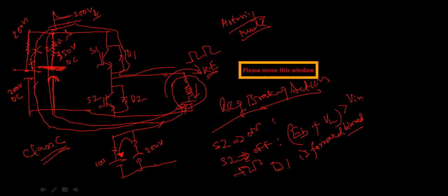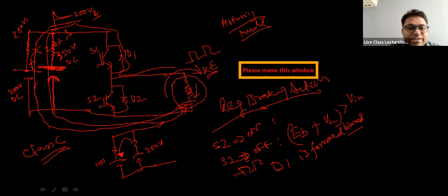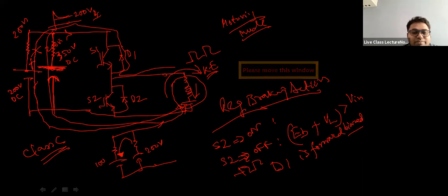The battery has a limited number of charging-discharging cycles. Only a very small quantity of power can be held by the capacitor, and the energy density of a capacitor is very high, but it cannot charge the battery like that. If you just keep it like that without going to motoring mode, hardly will it be able to charge it to 1%. So don't think that all the regenerative braking energy will recharge the battery. Forget that.